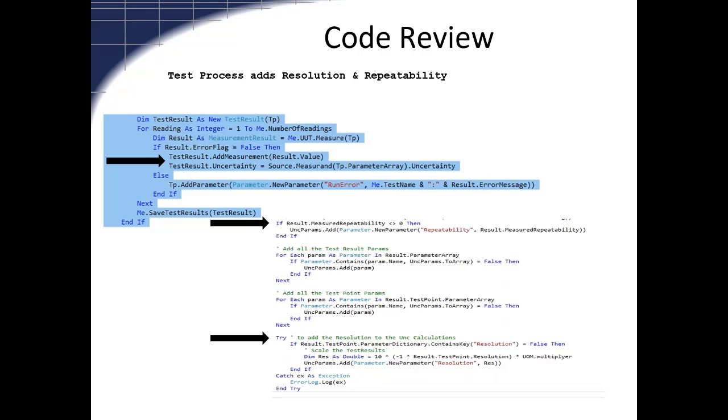When we're using a 5720 and we're setting the resistance value, and we want to get the current resistance value of the calibrator, this is the callback that we make, source measure, and that will give us the uncertainty and the actual output value of the calibrator if we needed that. Because we're sourcing DC voltage, we don't have to ask it what its value is. We can see that being stated.